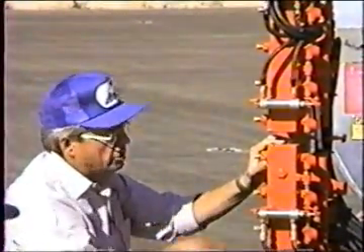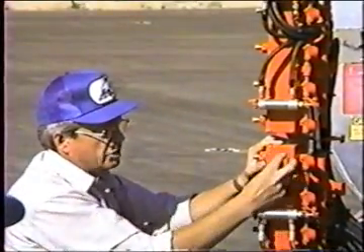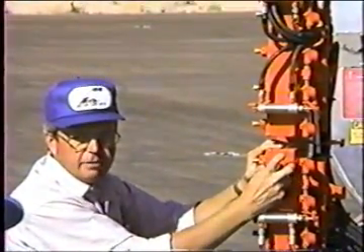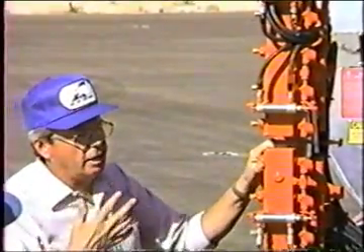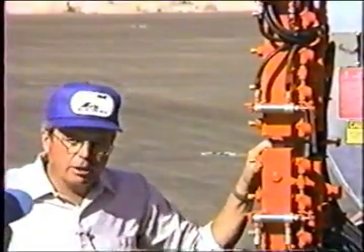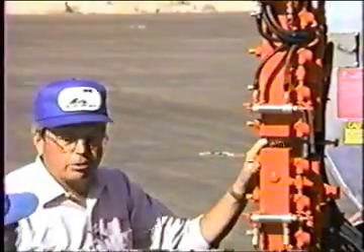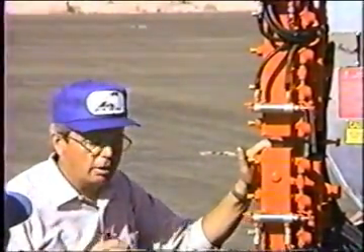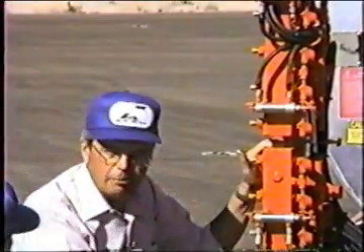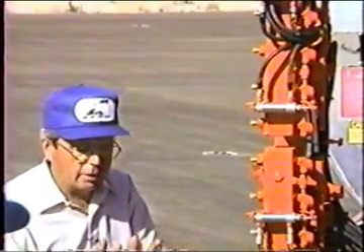Everybody else has a valve external on the spray bar. Their spray bar is circulating, but the valve has a neck between the bar and the valve. That neck cools off, the valve cools off, and if we sat here today in this cool breeze and circulated for 20 or 30 minutes, all those little things would be plugged up, and when you turn the spray bar on, the first thing you get is a worm coming out, and then the worm gets wider and wider, and finally you have a fan.